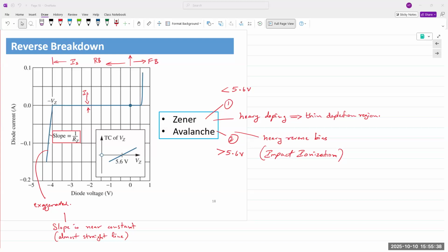The big property of Zener diodes is that they are used exclusively in reverse bias, because they function in reverse bias, meaning they are completely off until their reverse breakdown voltage is reached. Once their reverse breakdown voltage is reached, they hold the voltage constant across themselves, but can withstand large amounts of current. So they can divert large amounts of current through them while keeping the voltage across their terminals constant. And that is the big application of Zener diodes. That's why we use them for voltage regulation, to keep output voltages constant.